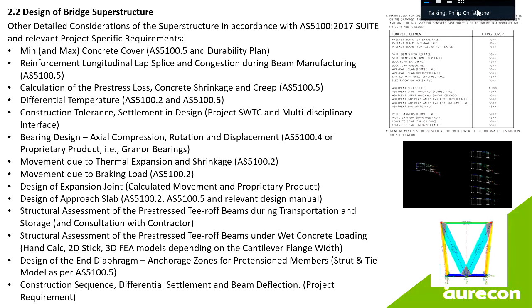So having different models set up now, it helps you to understand what the deflection, the SLS deflection is, and also the ultimate limit state bending. So you will be able to size the ligatures and the reinforcements accordingly.